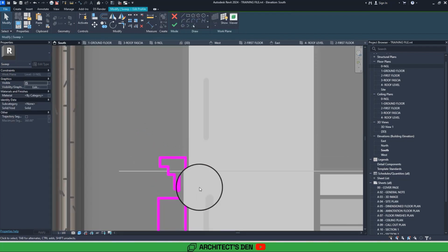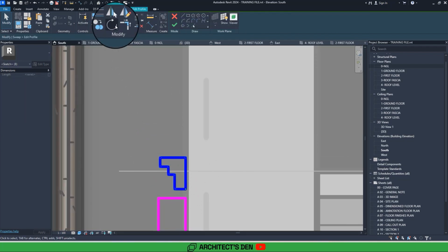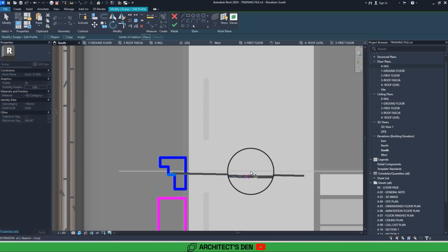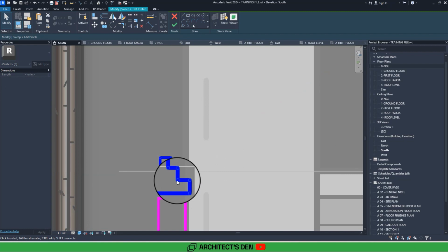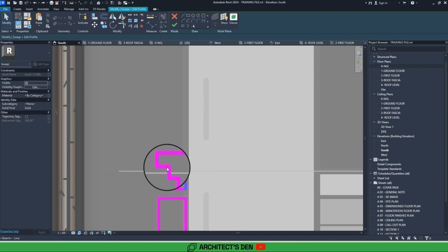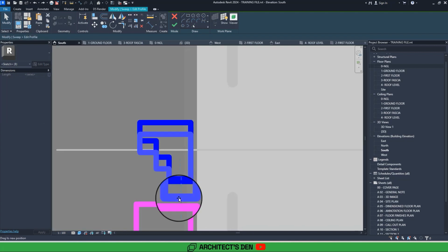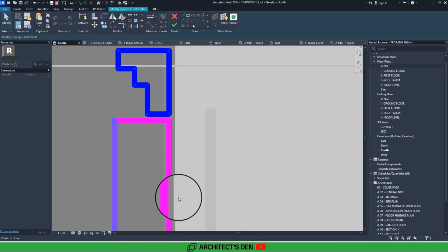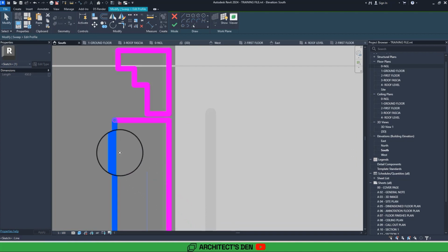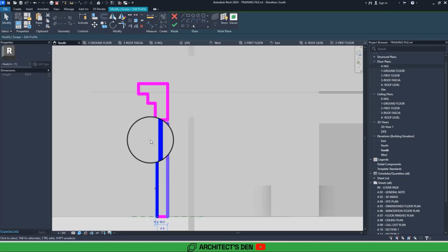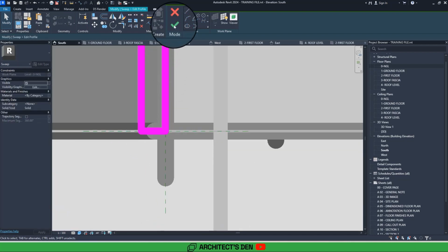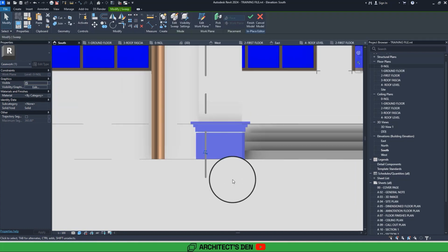So I'm going to turn it the other way. Select it, click on rotate. Then I can click a starting point, type in 180 degrees, flip it. No, this is not what I was thinking. So possibly what I should have done is to reduce this thickness, maybe to somewhere here, so that it's not that deep. So this is like 50 mm. I think this is better.